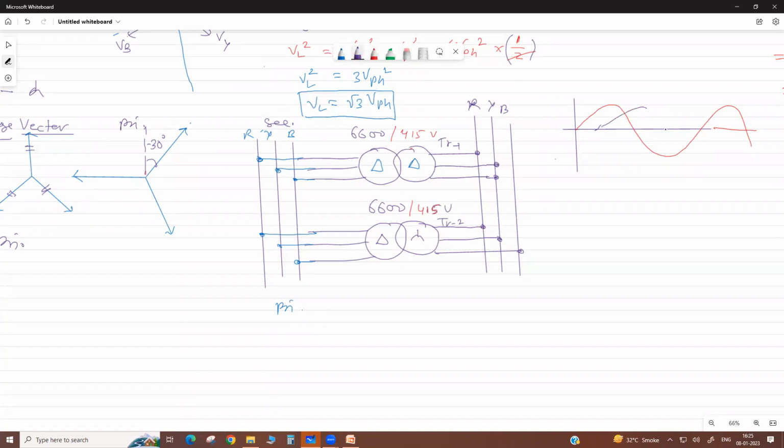You know why we synchronize two alternators? What is synchronization, and how do we synchronize? We use the 3-lamp method or the voltmeter method. What is its meaning? It means we connect the alternator to the bus bar when the bus bar voltage and the alternator voltage are in the same phase, meaning there is no phase difference.